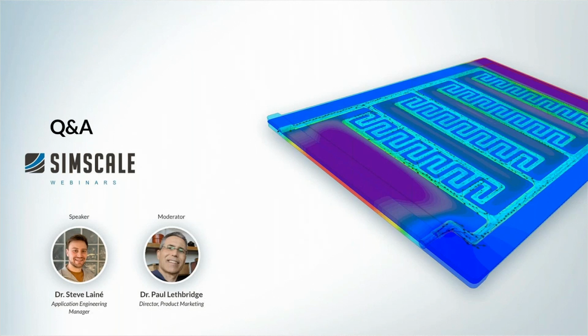We usually find it's best to start without radiation, start with the simplest possible simulation setup, and then gradually add complexity to your simulation to hone in on the most accurate possible result.